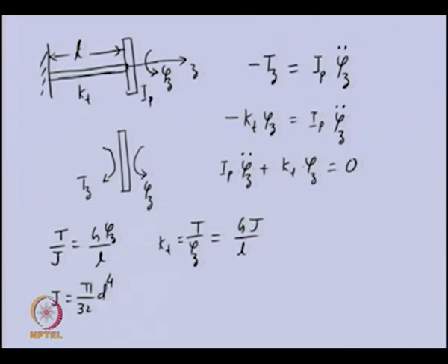And this is very clear from the previous understanding of the single degree of freedom system, we can say the natural frequency will be given by the stiffness divided by the polar moment of inertia, that is k by m. So, this is the natural frequency of a simple single degree of freedom rotor system for torsional oscillation. So, this is the torsional natural frequency.